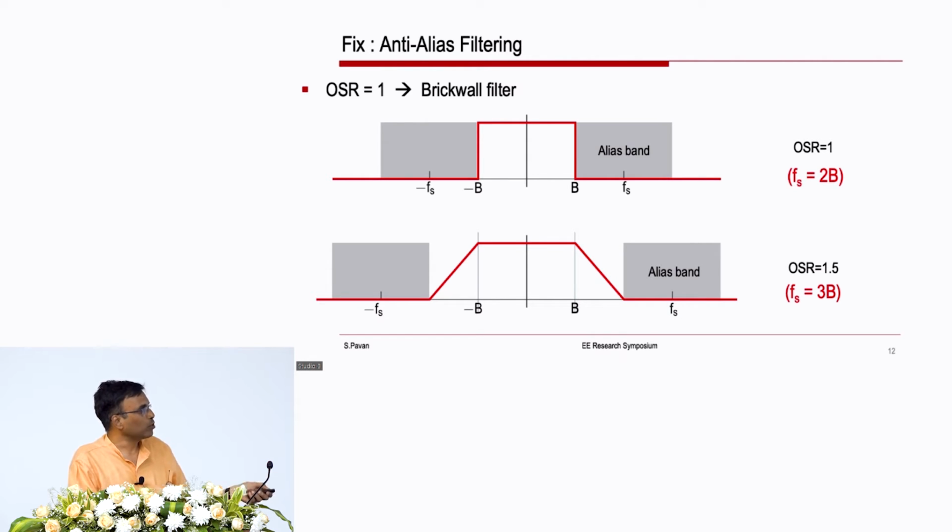So, now you see why Nyquist is okay in the textbook, but not in practice. If the sampling rate is chosen to be exactly equal to the Nyquist rate, this so called anti-alias filter must have a response which is brick wall, right. And anything in nature which falls off suddenly is impossible. The only thing you can do is make an approximation which approximates this brick wall, and so what is done in practice is you oversample.